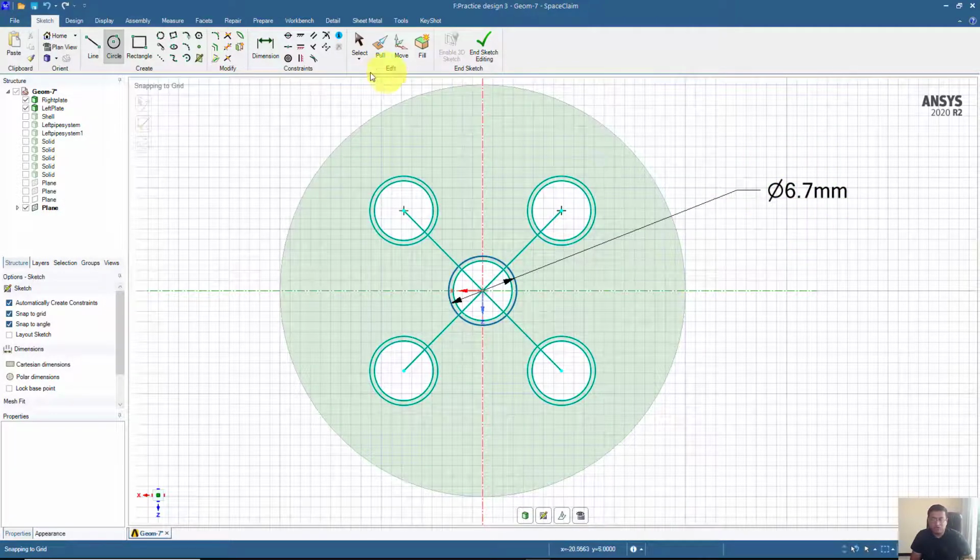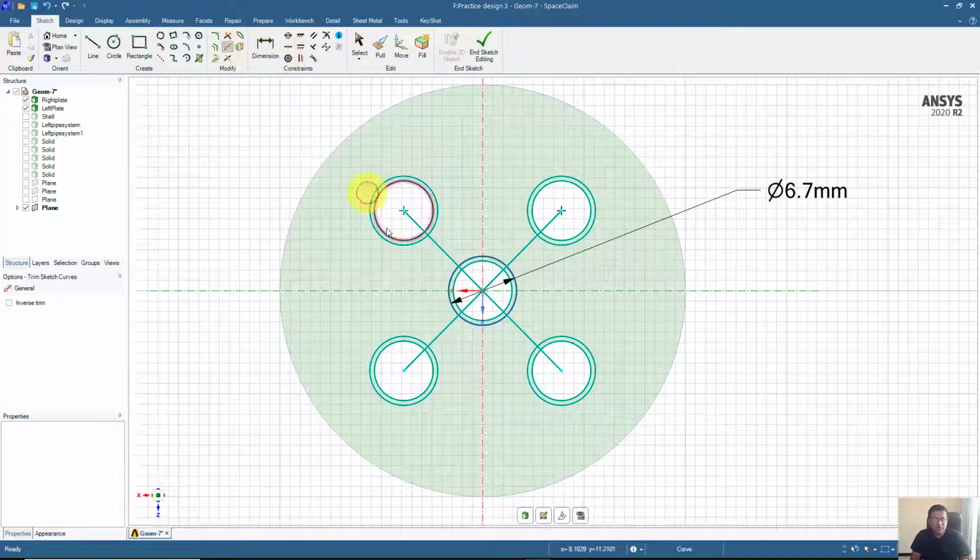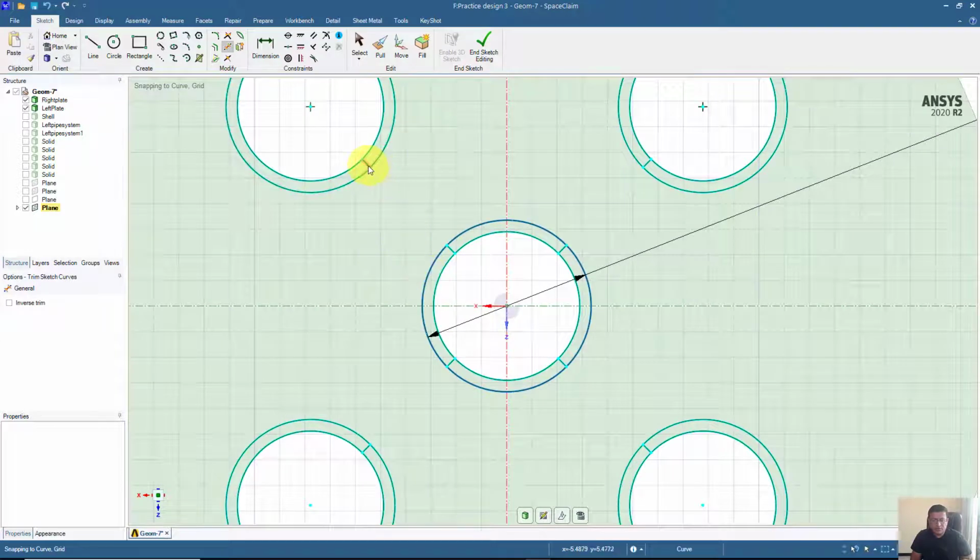the thickness of tube. And so before ending the sketch mode, I would be deleting the extra parts here, extra curves here. These are here. So these all curves which are used for the construction purposes are going to be deleted, and also these small lines here which are in between the thickness.